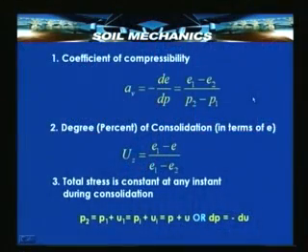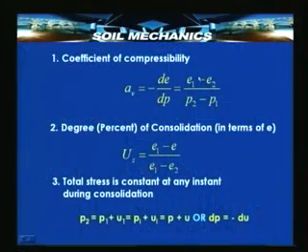Okay. Now, in order to evolve a mathematical formulation, in order to derive some expressions for this, what we shall do is define a series of relationships. To begin with, we have already seen that the coefficient of compressibility is a_v equal to (e1 minus e2) upon (p2 minus p1). This is a relationship which we have already seen, and it can be expressed in differential form as de upon dp with a negative sign to indicate that the change in void ratio is actually a decrease.